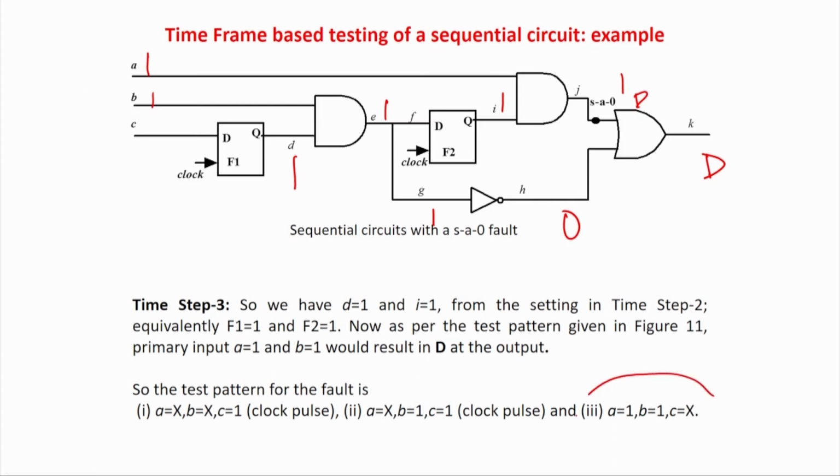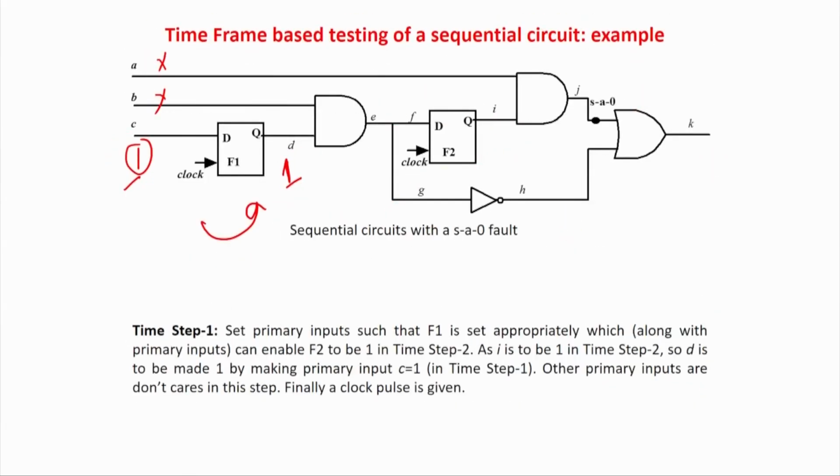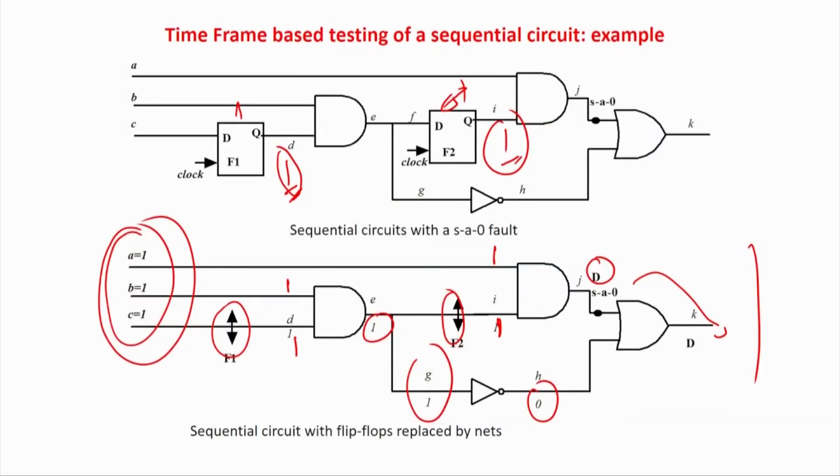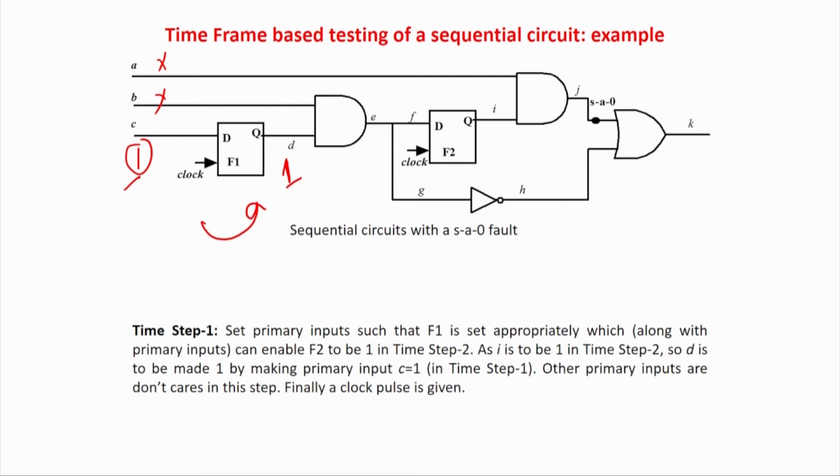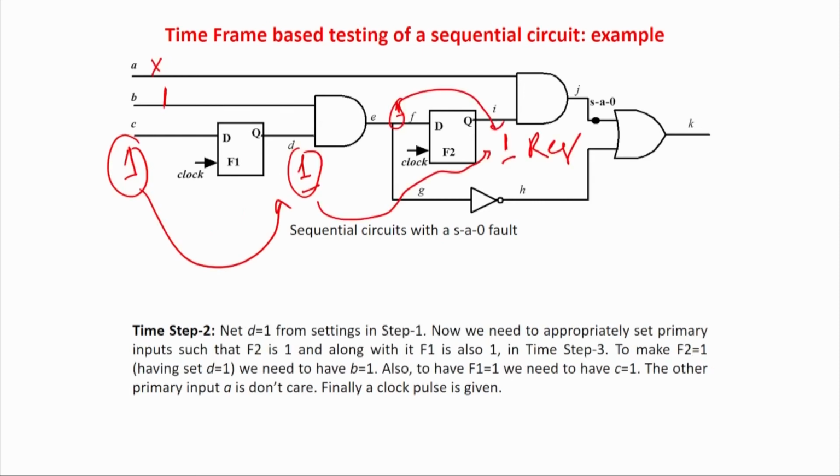In fact, this is the only test pattern required to test your circuit if you have a circuit with a scan. If you just take this raw circuit and run ATPG, it will give you a single pattern, and your job is done, assuming a scan is there. If you are not assuming a scan, then 2 more extra computations have to be done. Again, I am saying the computation has been done, which will tell you what to apply.